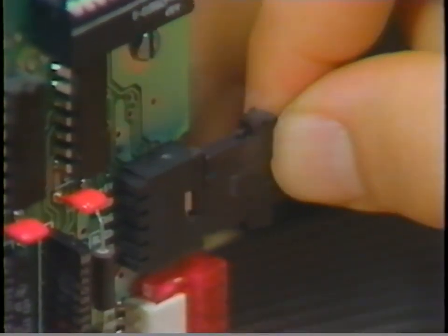This is J1 on the function board, the end of ribbon sensor connector. It is a 5-pin connector with locator lugs at the top and bottom. This is the system cable J2. J2 has 11 pins. Note that a pin is blocked at each end so the connector cannot be plugged in wrong. This is the control panel connector J3.